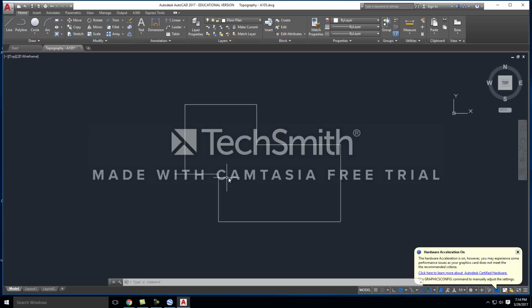Just like fillet, if you don't give it any dimension, it will just create a 90-degree bend. The difference between the two is that it's a lot easier to use fillet, as you're just hitting F versus CH. But if you need that kind of connection between your two different lines, you'll type in, actually, CHA is the shortcut for chamfer.